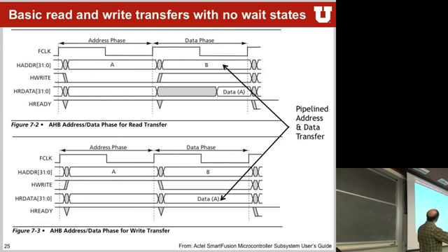In this case, AHB always has first an address phase and then comes a data phase. So the first clock tick that happens, the address has to be set up. The address has to be valid on the falling edge itself. And the next time we have the data phase, and the data has to be valid on a read on the rising edge again of that second data phase. So your peripheral has time, once it knows that it has to be addressed, up until the next clock tick to actually set up its data.